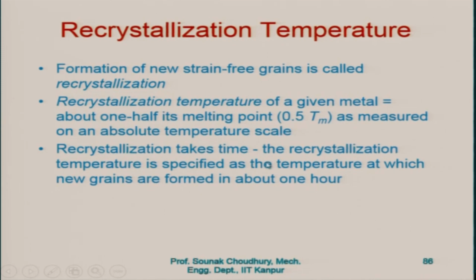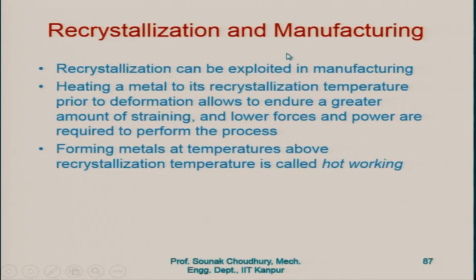Okay. Now, recrystallization of course takes time. The recrystallization temperature is specified as the temperature at which new grains are formed in about 1 hour. So, that time is specified during which this recrystallization process takes place and the new grains are formed. Okay. Recrystallization and manufacturing: how this recrystallization process is important for manufacturing is that